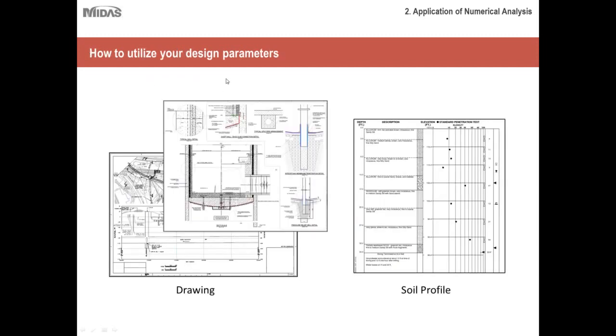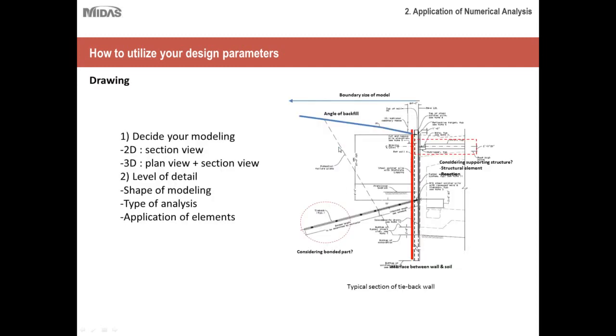Okay, how to utilize your design parameters. So here's some things that you need to have ready before you begin your numerical modeling. First, you need to have your drawings of your structures, as well as a soil profile. So these two things are key. It's important to have these two parameters ready for you before you begin your numerical modeling.